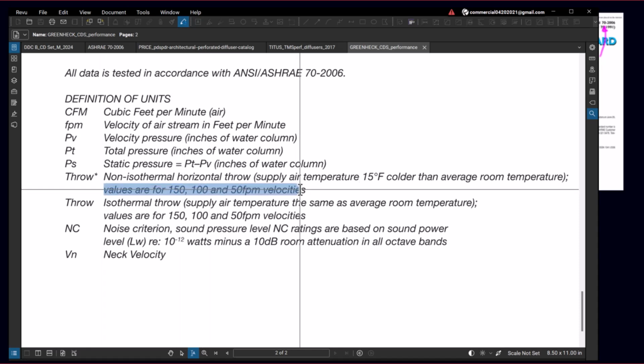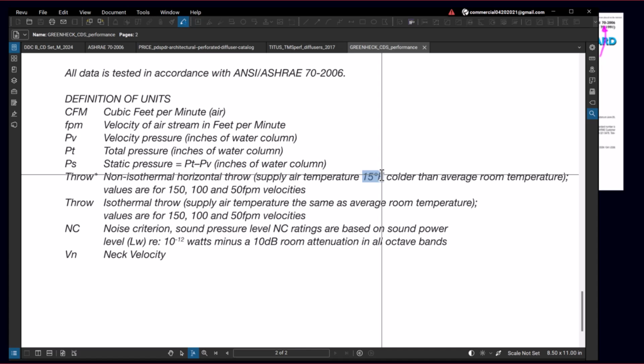So this is very interesting because there is a rule of thumb that says the following. You need to reduce the percentage by 1% based on the delta T. This is the delta T actually. 15 is delta T, 15 degrees. So technically that throw should decrease 15%. So if the temperature difference is 15, it should be 15% of decrease of the throw. There you go. So we're going to check that in here.